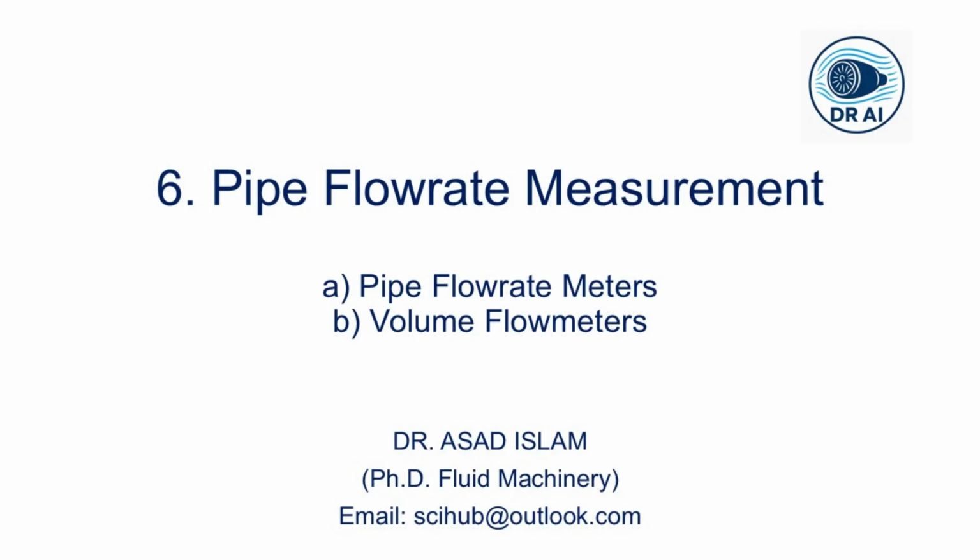Next time we will look at how we measure the flow rate in pipes using devices like orifice meters and venturi meters, and we will see how our understanding of losses applies to those as well. For now, practice recognizing the type of problem you are facing. Is it type 1, type 2, or type 3? Are the pipes in series or parallel configuration? Once you know what kind of problem it is, the path forward becomes much clearer.